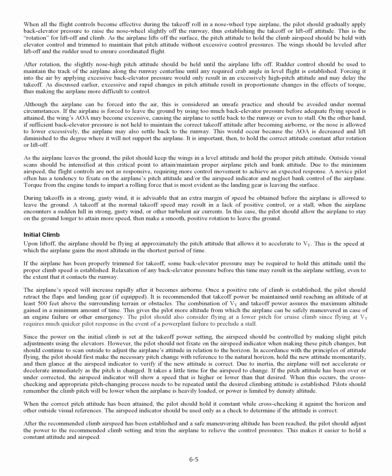Initial climb: upon liftoff, the airplane should be flying at approximately the pitch attitude that allows it to accelerate to Vy. This is the speed at which the airplane gains the most altitude in the shortest period of time. If the airplane has been properly trimmed for takeoff, some back elevator pressure may be required to hold this attitude until the proper climb speed is established. Relaxation of any back elevator pressure before this time may result in the airplane settling, even to the extent that it contacts the runway. The airplane speed will increase rapidly after it becomes airborne.